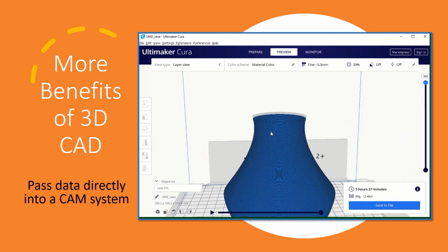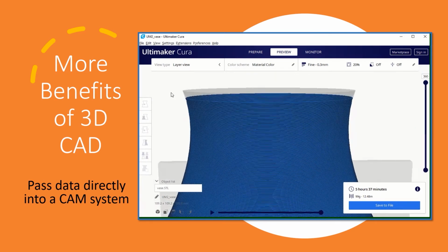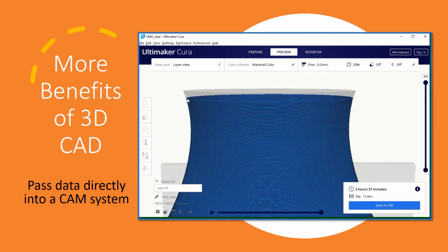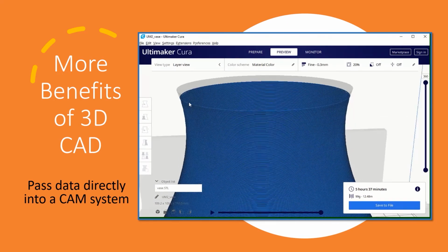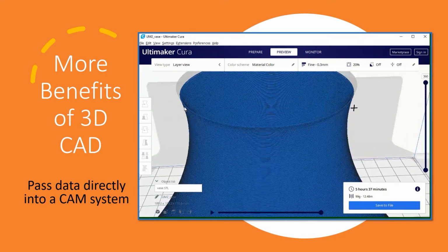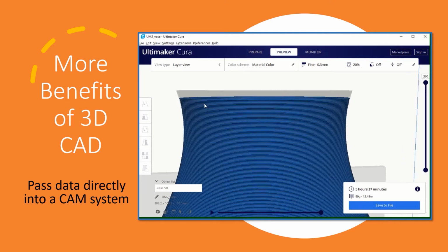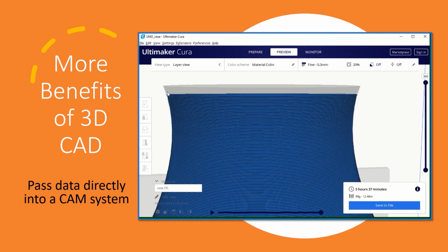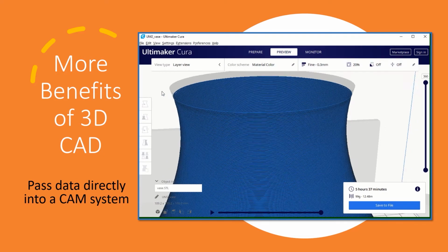Now, just something interesting that I've just spotted. Can we see here? This is the top of my model. This is the top of the 3D print. Now, why do you think that has not gone all the way to the top? Any ideas? You've probably guessed it correctly, because this thins out so much on top, it's thinner than the thickness of the extruded nozzle, which is 0.3 millimeters thick.